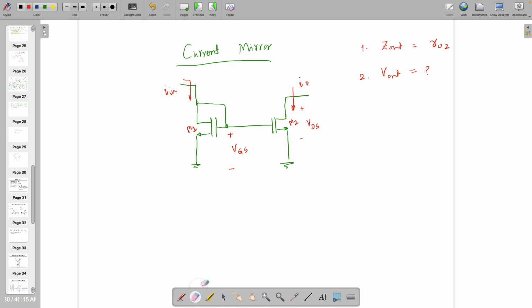What about V out? VDS you are writing. These two things we can keep over here. By the way, this is not exactly VDS, but VDS set. What is the value of VDS set? Generally, with our calculation, it has to be more than 250 millivolt. You wanted to have it 0, but it's not possible to have it 0. This is what you achieve with the current source used by the MOSFET circuit, which is using the current mirror.